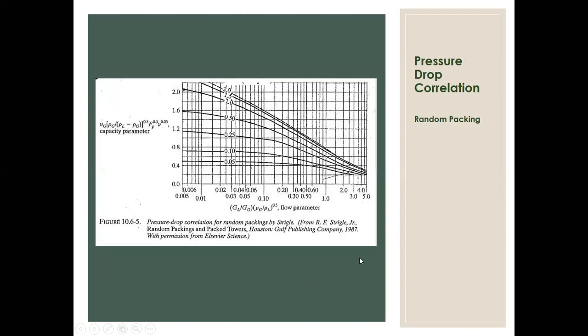Now, as for the pressure drop correlation, after you have determined the pressure drop, we can determine the linear velocity at flooding, the V that was mentioned in the last 2 slides, when we do not know the pressure drop. These curves that you see are actually the delta P's. We determine the abscissa, or the x coordinate, of this particular graph.